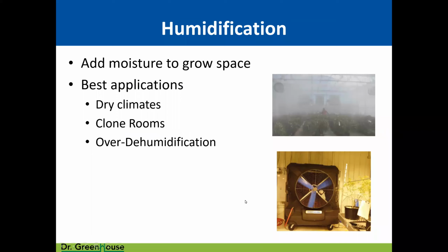Okay, humidification. All right, we're adding moisture to the grow space, right? Best applications are dry climates, clone rooms for those of you cannabis growers, also anyone doing grafting or working with plants that don't have root systems yet. We tend to want a more humid environment in there.